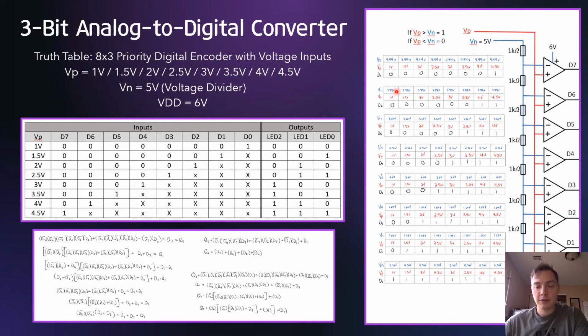And so the first thing I did was I created this schematic over here. I know you can't see it because my face is in the way, but I started with the schematic. I created it in Microsoft OneNote, but I started with this voltage divider. So I took 5 volts, divided it up in between 9 1K ohm resistors, and after each voltage drop, there's a different voltage found at each of these nodes. So the first one would be 4.4 volts, 3.88, 3.32, 2.76, and so on. And those voltages are all connected to the negative terminal, and those are what you're comparing to.